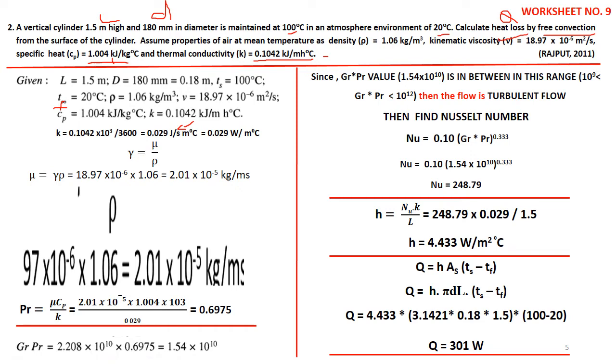Okay, then you will get 0.029 watts per meter degree Celsius. Okay, K. Then here dynamic viscosity is given. I have to find mu, the dynamic viscosity. Why? Because then only I can find the Prandtl number, right? Because Prandtl number is mu Cp by K. So how to find dynamic viscosity?